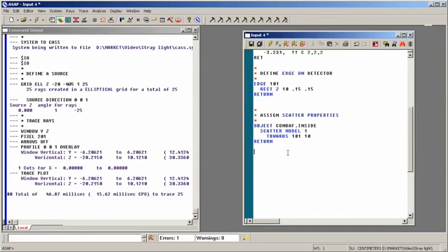Let's put our rays into our system. Define source. Grid elliptic Z, again, it's at Z equal minus 20. That's the entrance to our system. It's a semi-diameter of 6, so we're going from minus 6 to 6 in X, minus 6 to 6 in Y, 1 ray in the X direction, just for simplicity, and 25 in the Y. Source, direction, 0, sine 20, cosine 20. And do our ray trace.